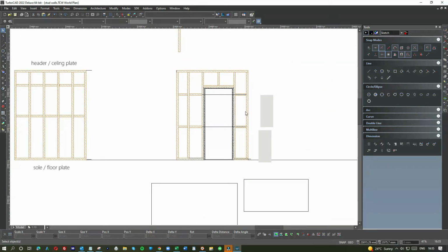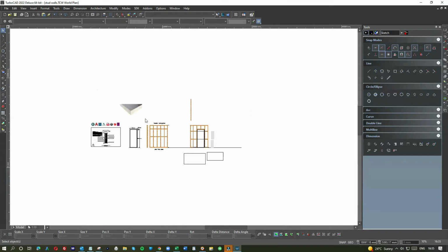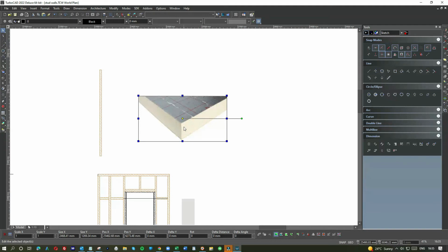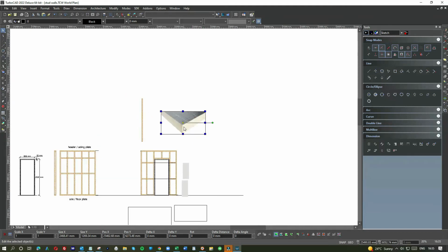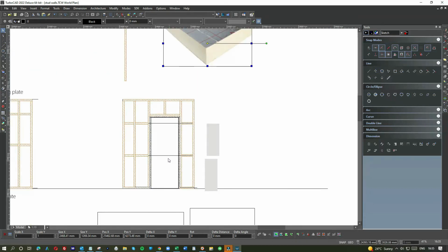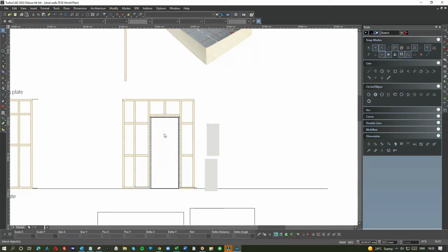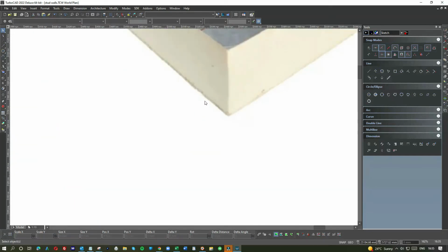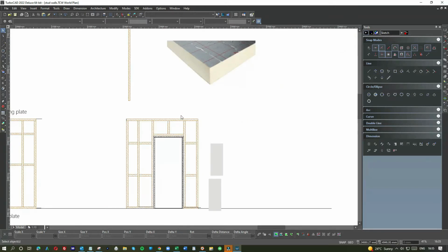That's actually it. So normally what you'd do now is you'd get your Celotex. This is actually a fairly thick one. It looks like about 100, maybe 125. Normally what we would do is cover one side of the partition if we were building. Then you fit this Celotex, cut it into squares. You can cut it with a saw, it's very easy to cut. Pop it into all the openings, and then once you've done that, you start to cover this side.